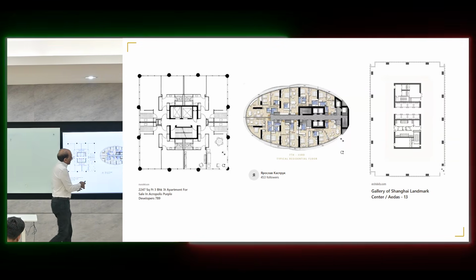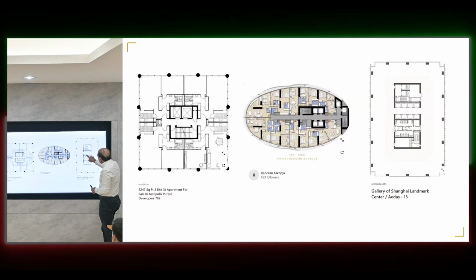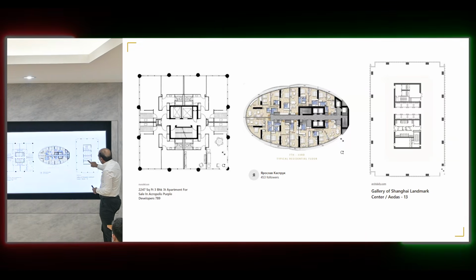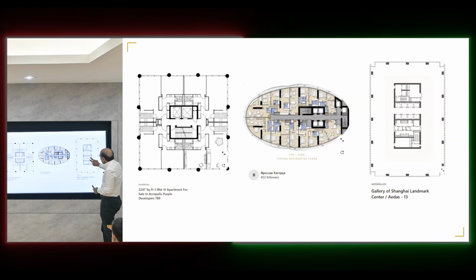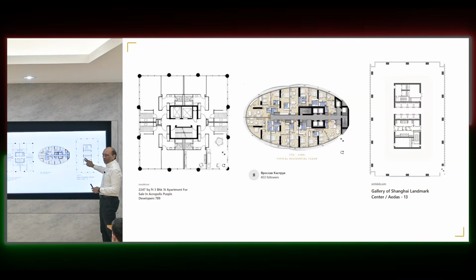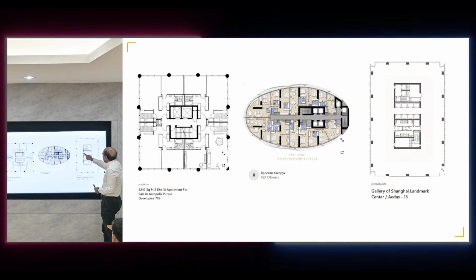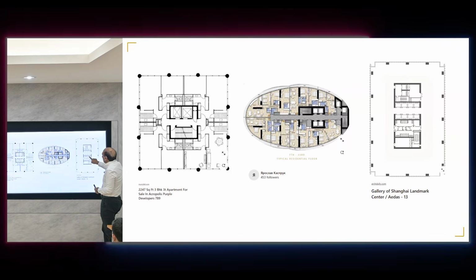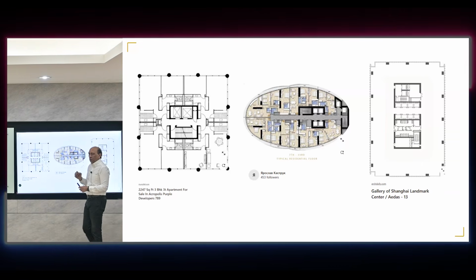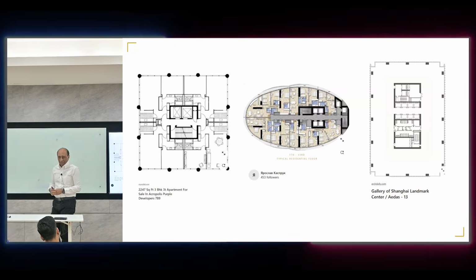So this is, once again, as you can see here, the core is very clear. In the small portions inside, there are many walls, but the engineers cannot use those walls, because as soon as you use them, you have to make them thick, and then they take up space. So they are all partitions. Only the outer few walls are strategically chosen to take the bending and shear, especially the shear.